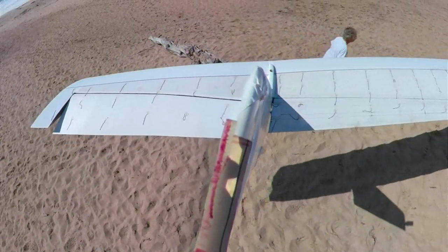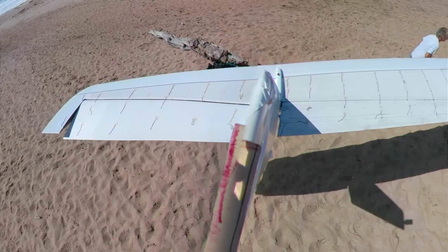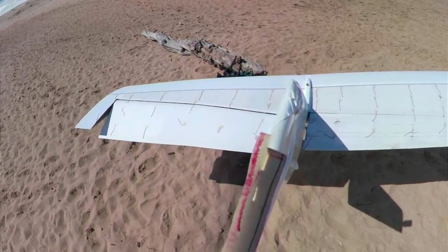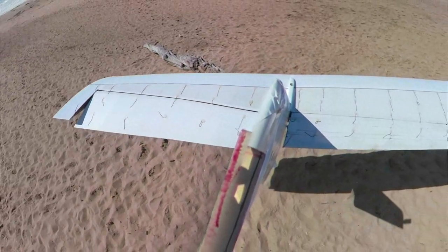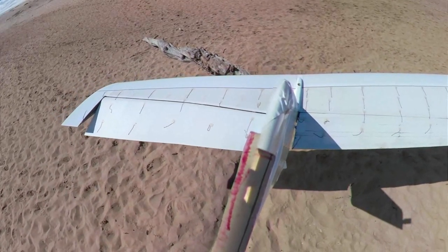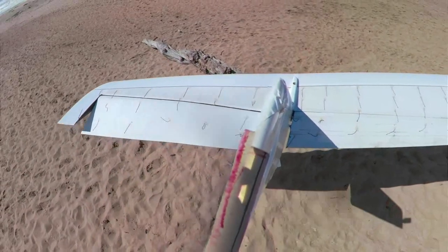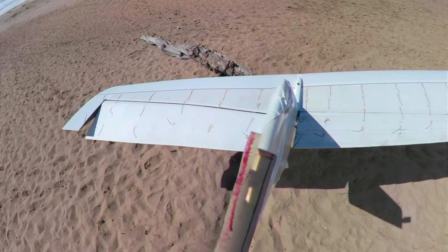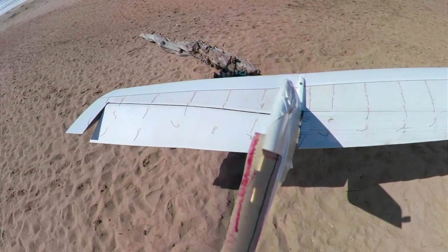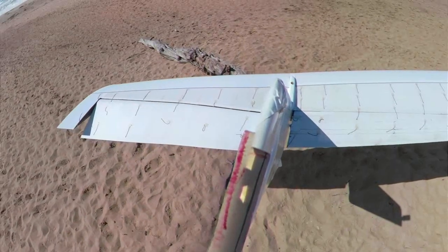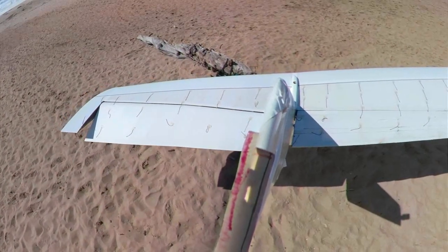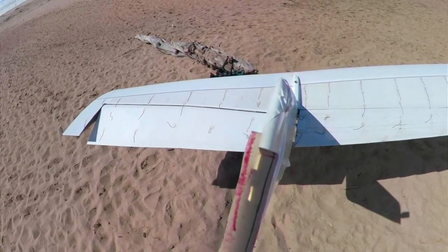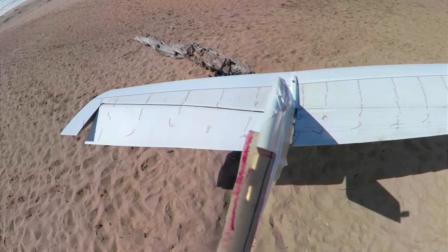And there we see some of that classic second half of the elevon flow separated on the inboard portion, and the tufts go out 90 degrees. Now at the tip of that elevon, we see that the tufts are still pretty well behaved, and that's because I'm using the higher energy flow near the spar and asking that to go around the corner instead of the lower energy stuff. As you get inboard, that hinge line is further away from the maximum thickness point of the airfoil, and the flow is already into the adverse pressure gradient, and then we're asking it to turn a corner.